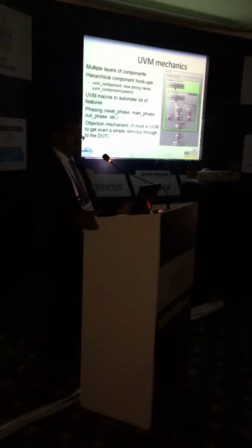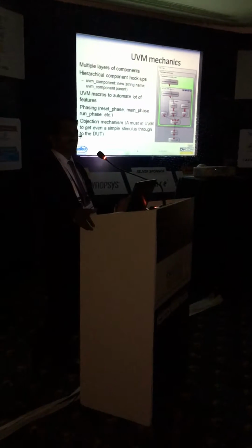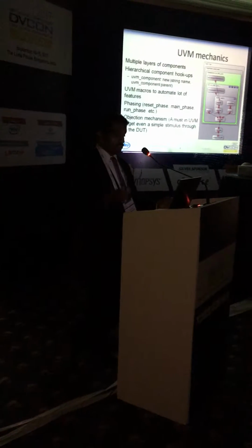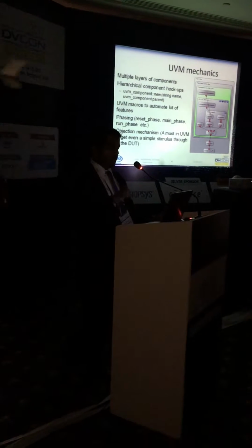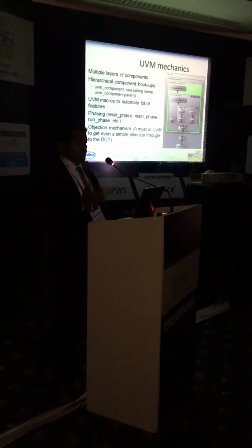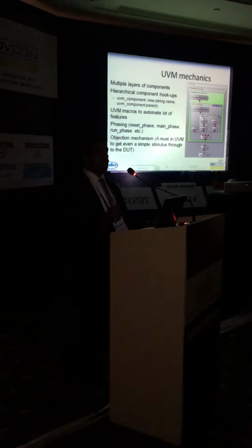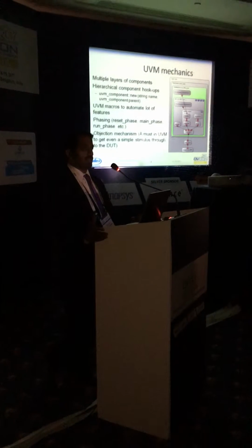And for those who have used long back this VMM and OVMs, the objection mechanism really crept into UVM. It's actually a great thing, according to me. But then the way it works today, if you do not put an objection and you have a delay in your test, somewhere you do have it. If not a hash delay, but you do have a clock delay. And unfortunately, the way UVM is architected today, it would not tell you anything, and it would simply quit. It would not honor any of your delays unless and until you have an objection mechanism.